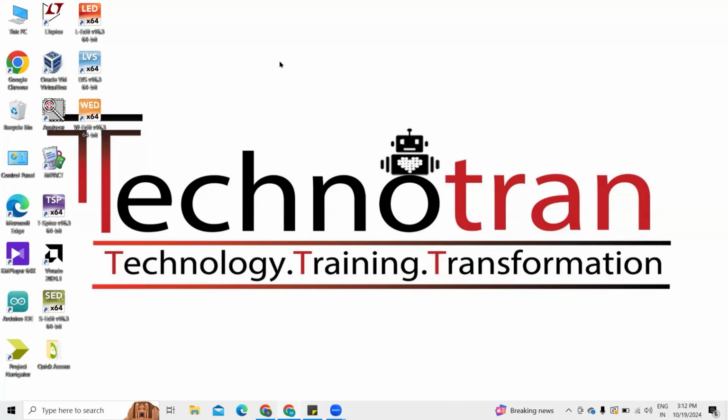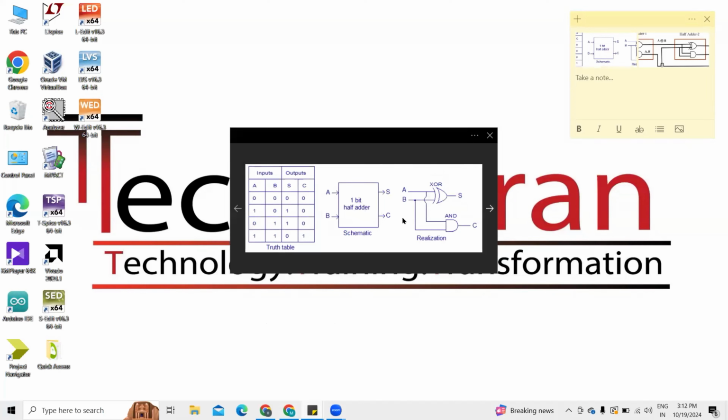A half adder is a basic digital circuit that adds two binary digits. So this is the circuit and this is the truth table of a simple half adder circuit. A half adder circuit consists of two input variables A and B. These two input variables accept binary digits, either 0 or 1. Likewise, it consists of two output variables, sum and carry. Now we will see how this half adder works.